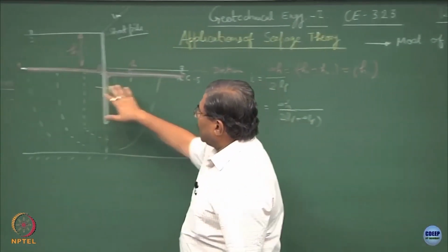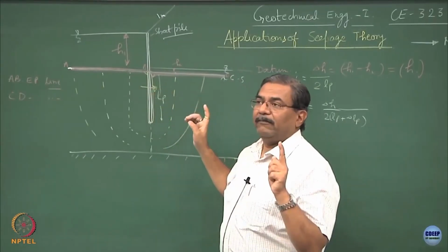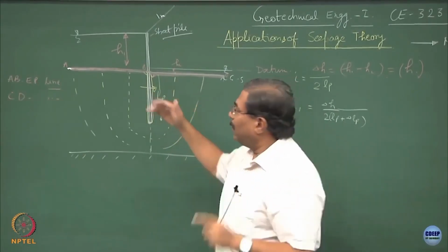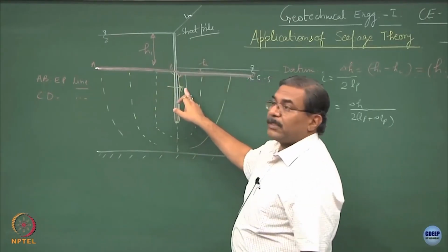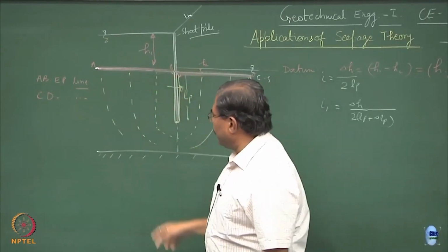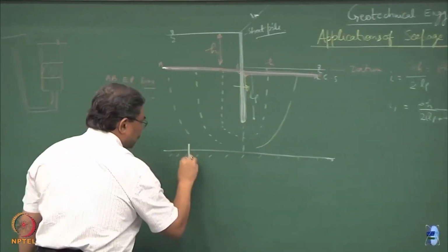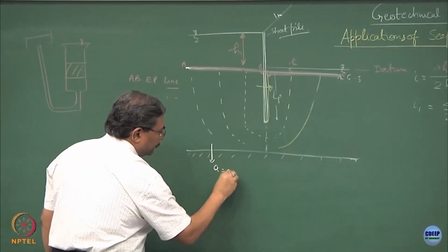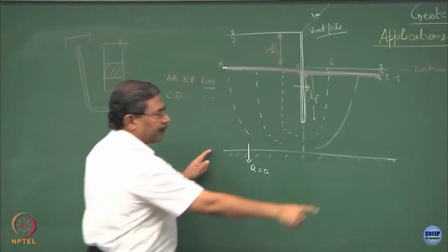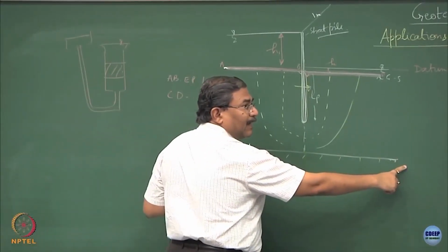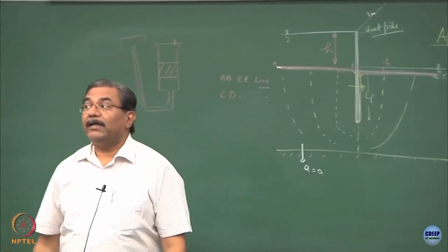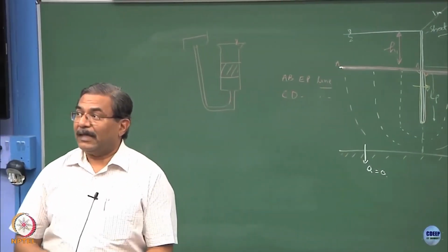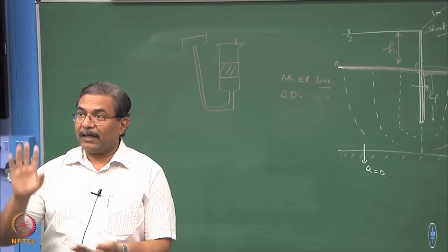So is this part clear? We have fixed the boundary conditions: equipotential line, flow line, and across this no discharge is going to take place, this is the porous media. Similarly across this there is no discharge because it is an impervious surface. Now if there is no discharge across this line, this is also going to be a flow line, agreed, correct.